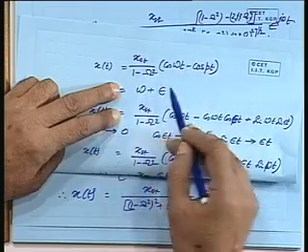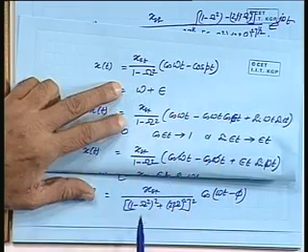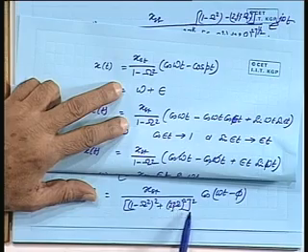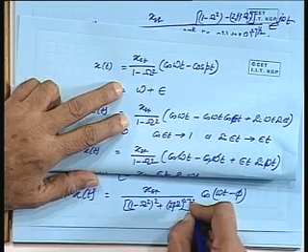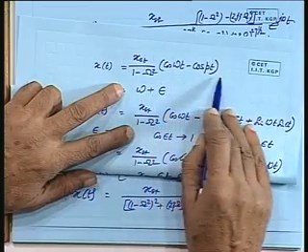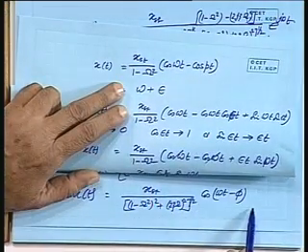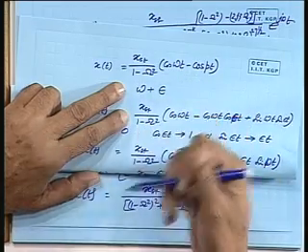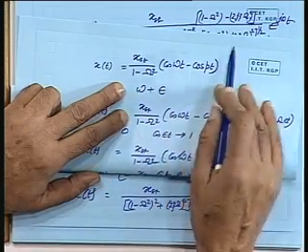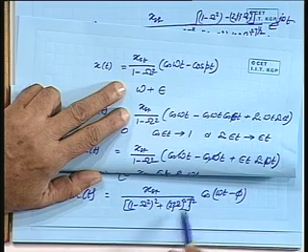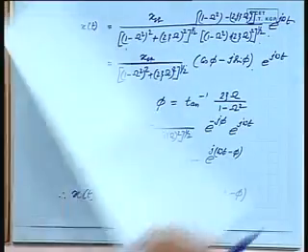So, what you are getting here is 1 minus omega square, what you are getting here is 1 minus omega square whole square plus 2 zeta omega square root of this. Okay. You were getting cos omega t term here, you are still getting cos of omega t minus phi here. There was a natural frequency which would have died down, so we would not have bothered about it. So, there is a phase lag coming here. Okay. So, this is an additional term, this is the term you are getting.